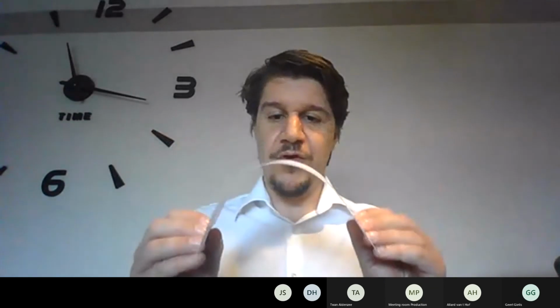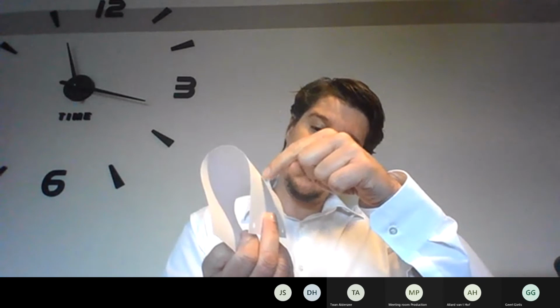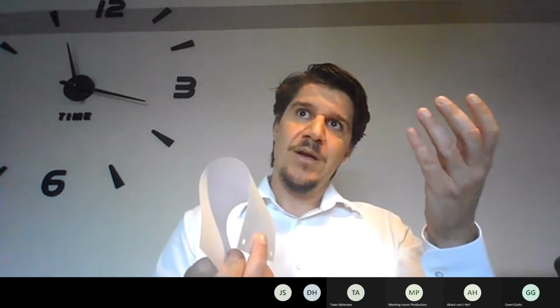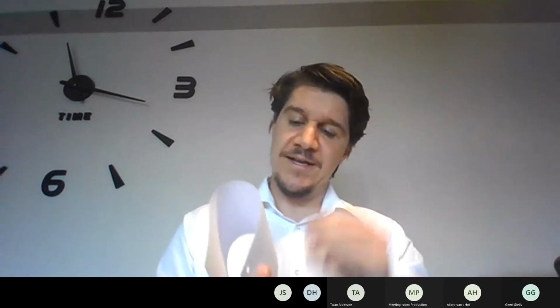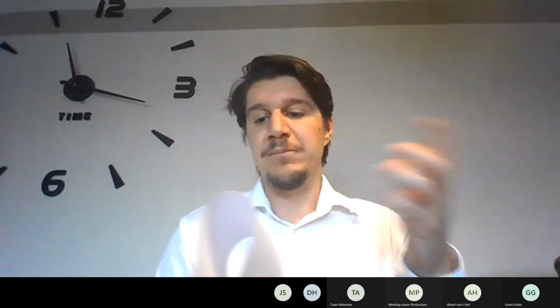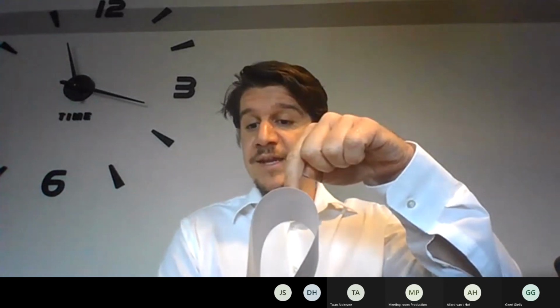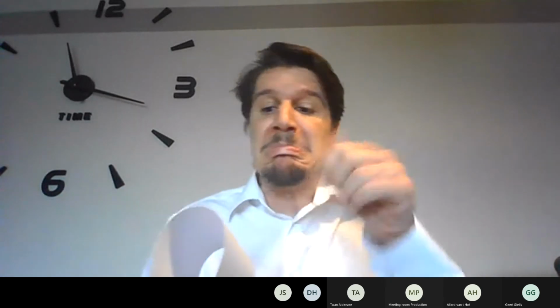So here again, from the top, the pad is here. So you look from the top. That's a perfect angle. You see it. No need to move the camera in Z, whatever. It's fine. But now let's take a pad which is here on the side. What historically was done is that you move the head in Z to be in the focus of the camera, normal. The problem is that you are looking at a different angle here or on the other side than you do here. So you see one side, but the other side you don't see it. So what will you do?